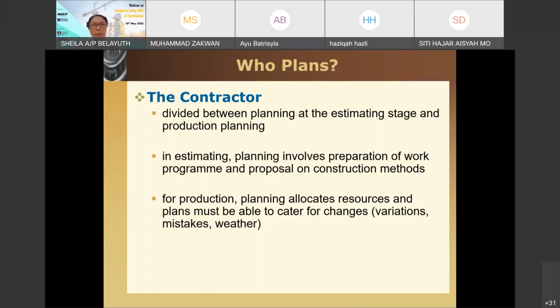Quite difficult. So that's why, to be a very balanced engineer, to be a good designer, you need to at least know, or have the experience, of how it will be built on the site. Otherwise, sometimes we place the reinforcement bar without thinking: would it be difficult for the contractors on the site to actually assemble? Will that actually create a honeycomb?